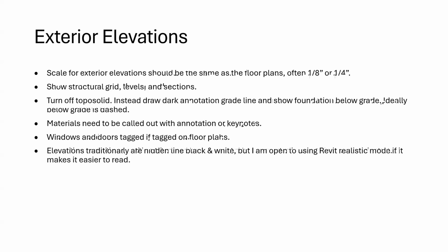My theory on exterior elevations is that I turn off the topo solid because I want to see the foundation below the ground. Instead, I draw a dark annotation grade line and show the foundation below grade. In a perfect world, the stuff below grade is dashed. I'll show you how to do that as part of the assignment we're going to talk about today.